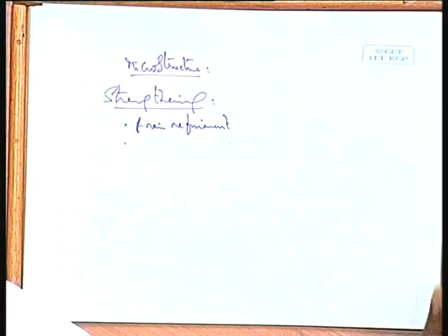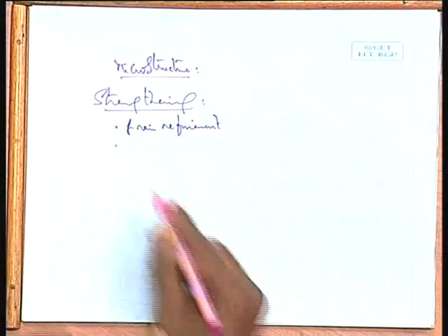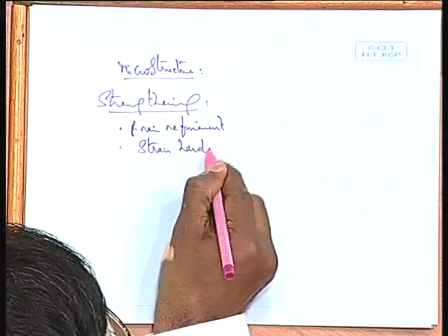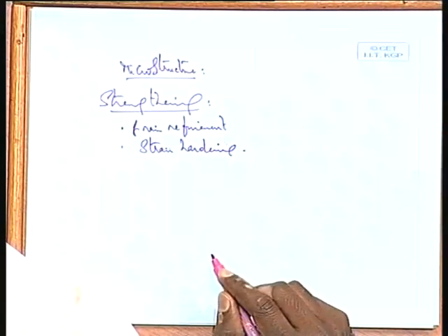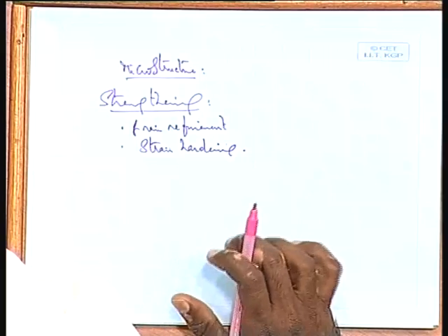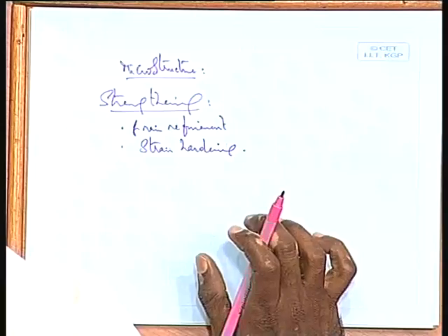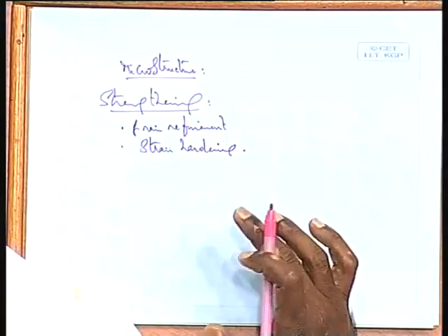Pure metal, how do you precipitate? Cold working or strain hardening. How does the strain hardening occur? Dislocation interactions. So, when you have too many dislocations, each dislocation acts as an obstacle for dislocation movement, and we all know strengthening mechanisms are basically mechanisms by which we can restrict the movement of dislocations, because it is the dislocation which is crucial for slip to occur.